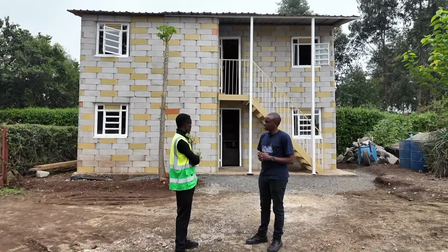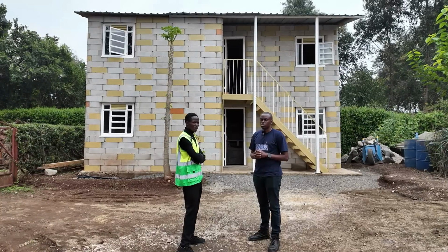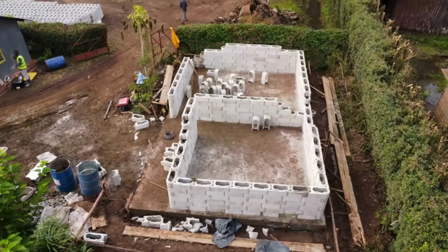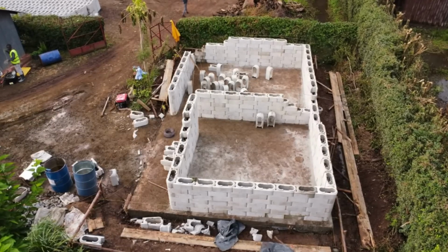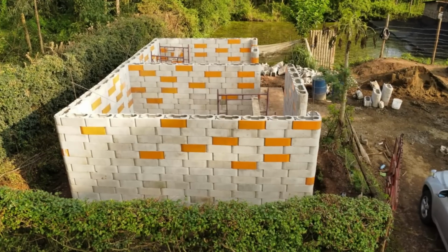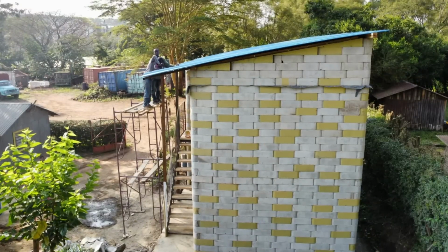Well, this was a very special case. Now that we didn't have reinforced concrete for the columns, it took us 4 days to do the entire walling from the first course to the 36th course. The back side of the structure has 36 courses. The front side has around 28 courses, so that you achieve that slope for the roof itself.